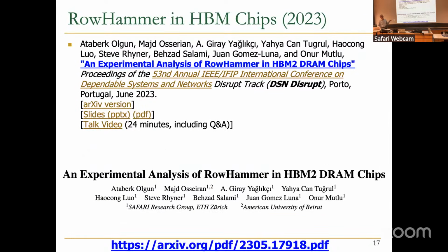So understanding RowHammer is actually very important because RowHammer is a problem in any kind of DRAM chip, including HBM chips. HBM chips are high bandwidth memory chips that are used in essentially all AI infrastructure today. All of the AI accelerators, machine learning accelerators have HBM because it's high bandwidth, and you need high bandwidth to fetch the data at high throughput for these machine learning models. GPUs have all HBM, and RowHammer affects all of those HBM chips very similarly to how it affects the other DRAM chips. The main difference of HBM and other chips is the interface.